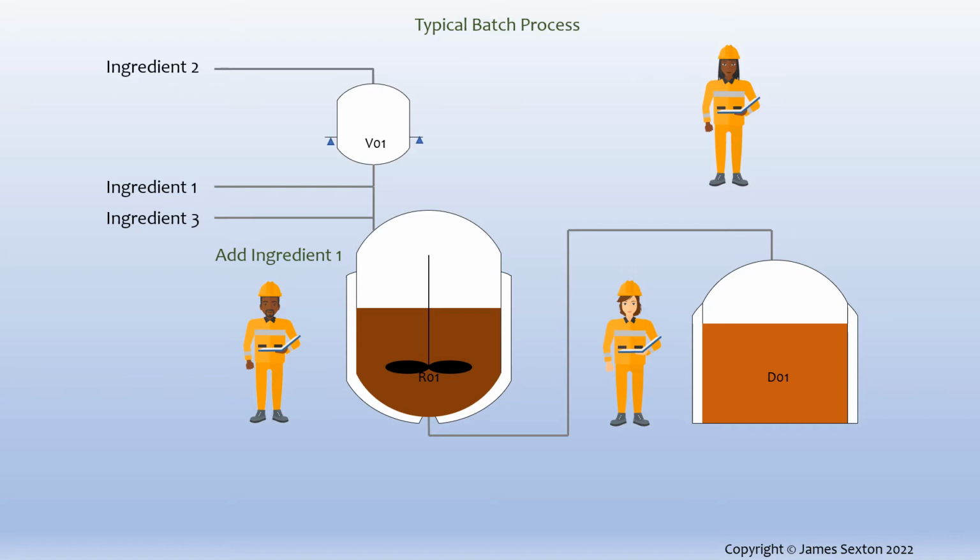But there's one more improvement that's possible. Notice that after the addition of the first ingredient, the reactor has to wait on the second ingredient being added to the weigh vessel V1 before it can be charged to the reactor.